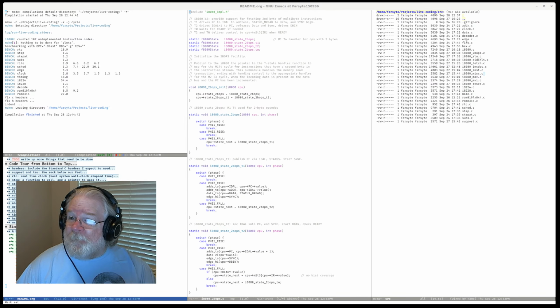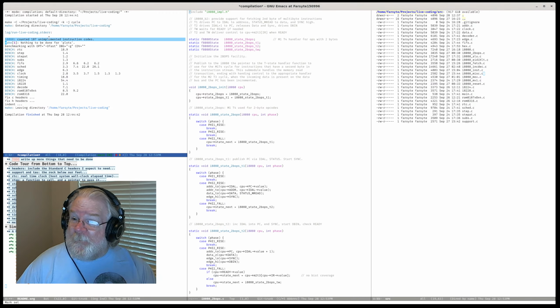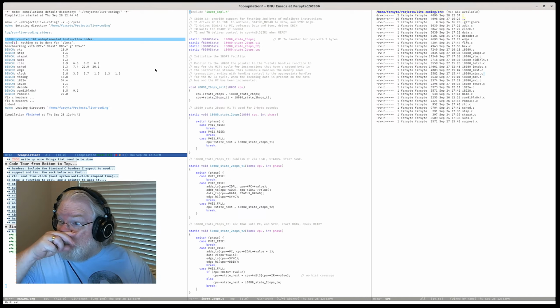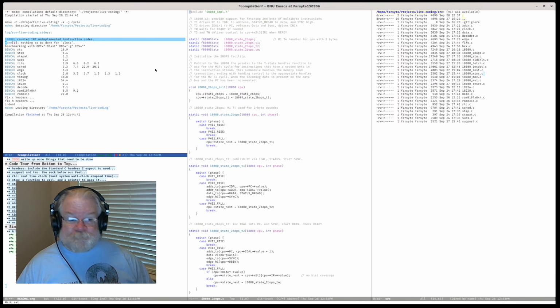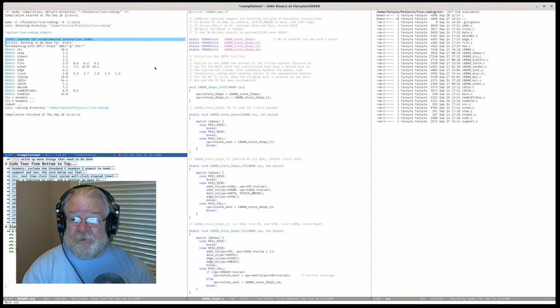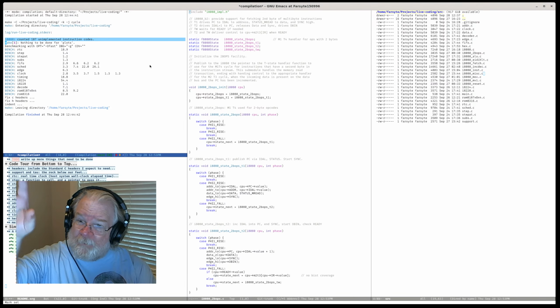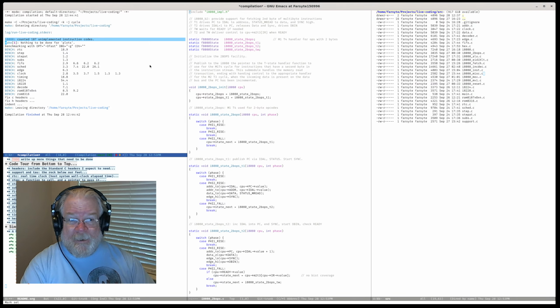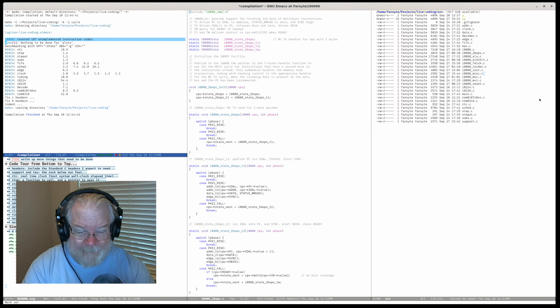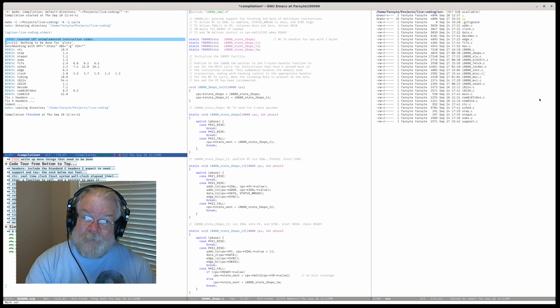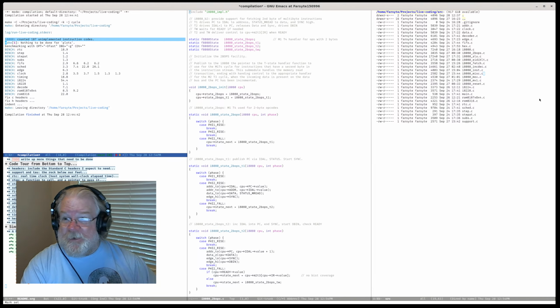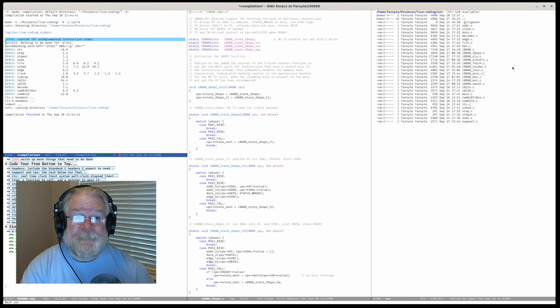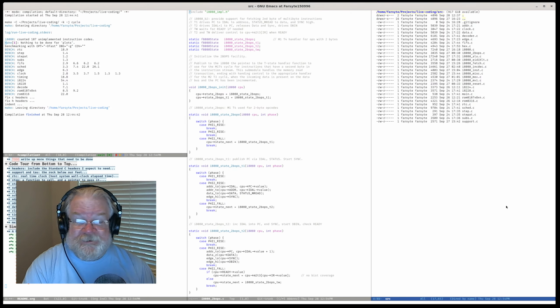And you can see in the upper left that when I do the build, I am actually printing out how many individual instruction opcodes I have not yet implemented. Now, there are some unimplemented instructions in the 8080, but we're at 107 to go. So it's probably a dozen, I don't know. There's a column of 7 right at the beginning, and there's a few others scattered around. As we close in on that, I may set up a handler for those instructions to recognize them as illegal instructions, so they will disappear from this unimplemented instruction code list. We may even use them as special trap instructions to cause the simulation to do something fancy. Who knows?